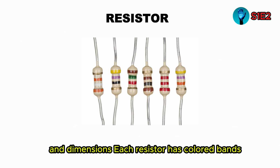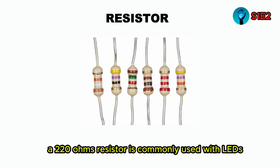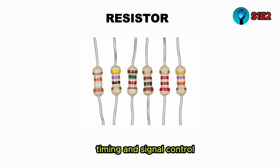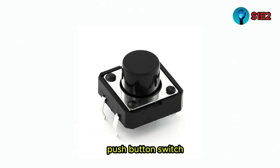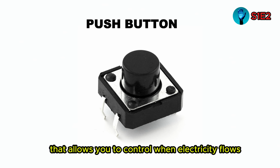Each resistor has colored bands that represent its resistance value. For example, a 220 ohm resistor is commonly used with LEDs to prevent them from drawing too much current. Resistors are essential for voltage division, timing, and signal control, making them one of the most fundamental building blocks in electronics.